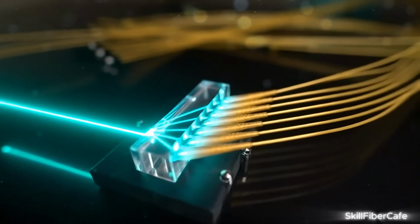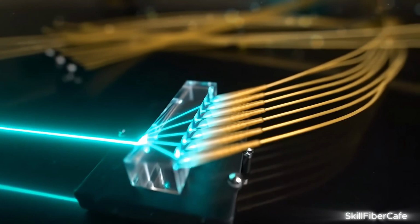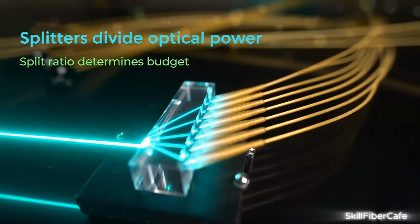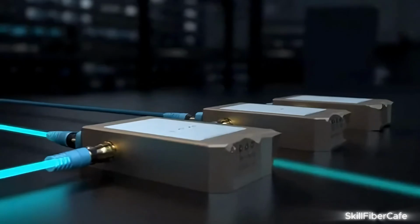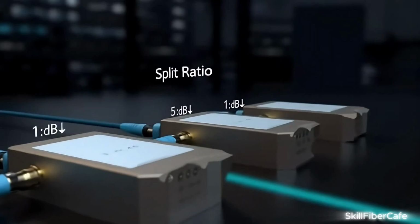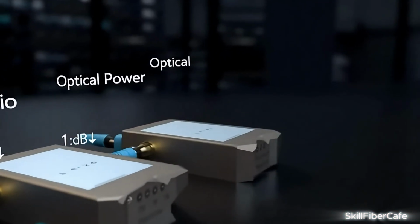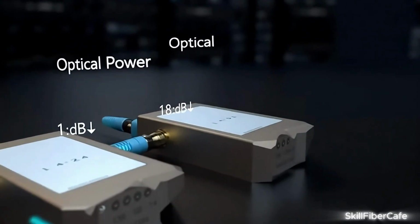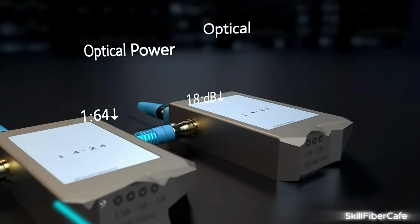Splitters divide optical power among many users, but division means attenuation. Energy shared is energy reduced. That's where split ratio becomes vital. A 1:16 splitter loses about 13 decibels, 1:32 around 15 decibels, and 1:64 nearly 18 decibels. Each step expands coverage, but shrinks available power.